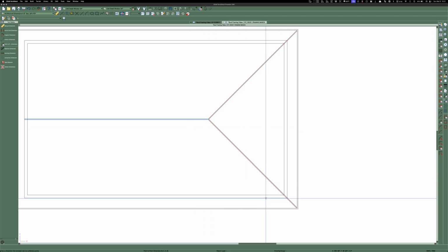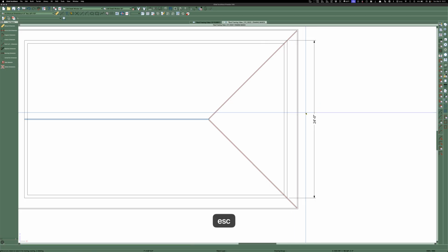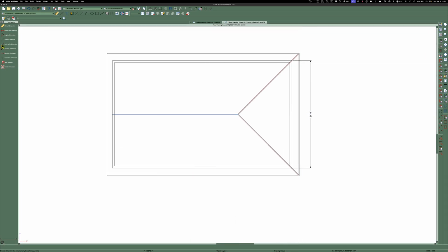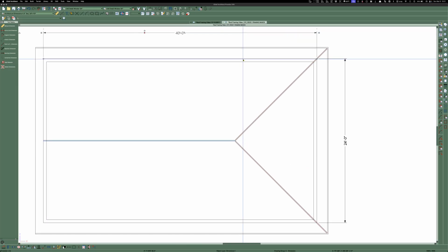So the building is 24 feet. And I believe he had said it was going to be like 40 feet that way. Okay, good. So what you have to do is take this, which is called the span. Whenever it goes from the outside of framing to the outside of the framing, and you're trying to do a roof, that's your span for calculating.